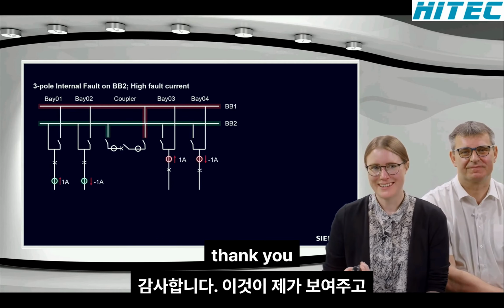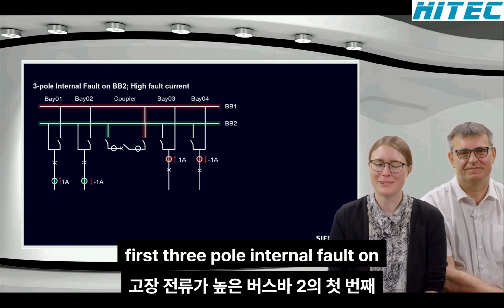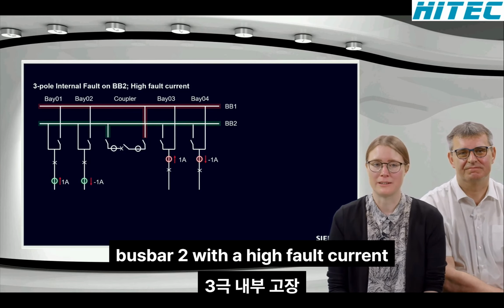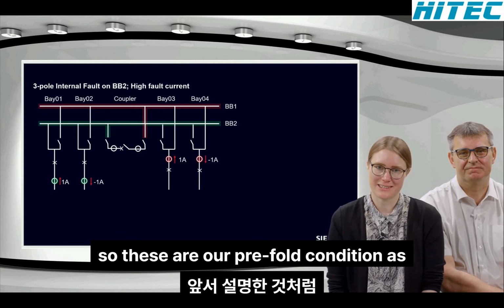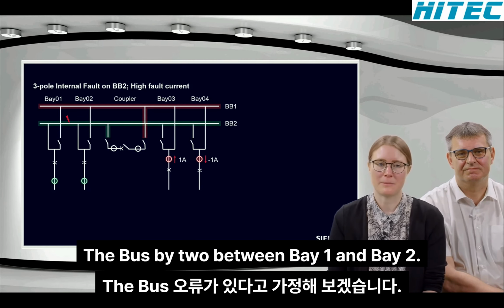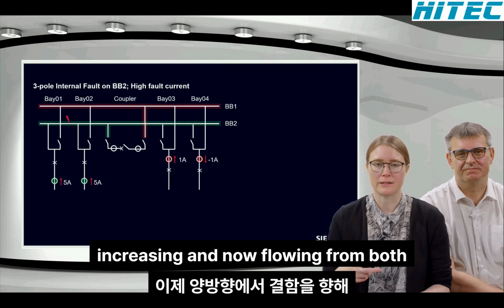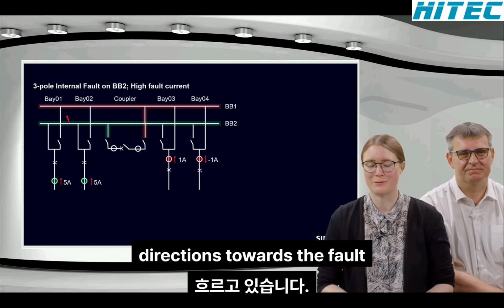Thank you. So this is what I want to demonstrate first. 3-pole internal fault on busbar 2 with a high fault current. So these are our pre-fault conditions, as explained earlier, with the coupler open. And then let's assume there's a fault on the busbar 2 between bay 1 and bay 2. And this leads to a current that is increasing and now flowing from both directions towards the fault.